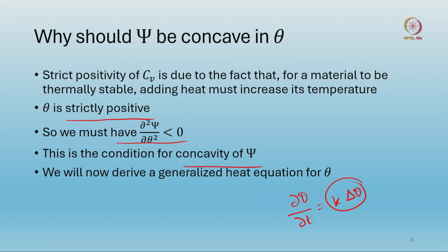The point I am trying to say is that this is also called the diffusion term, right? There is a reason for this, because the heat diffuses. If you have a very high temperature at a point in a solid body, slowly after some time the heat will diffuse, and therefore the temperature at that point will go down and the temperature elsewhere will go up, until the temperature everywhere remains the same and is equilibrated with the surrounding, the ambient temperature. Till that happens, this process will continue.